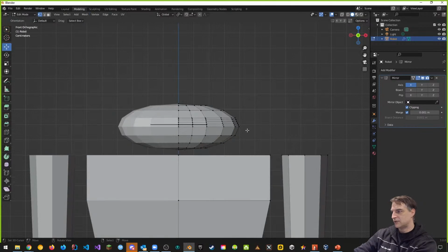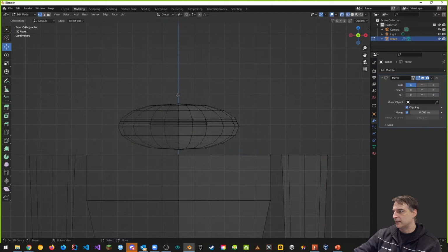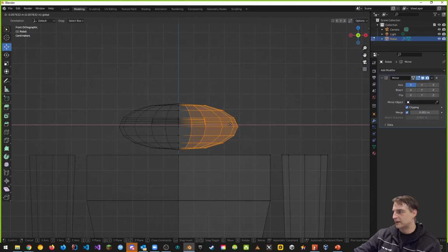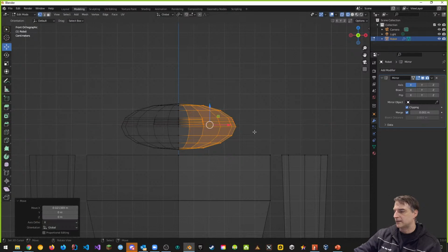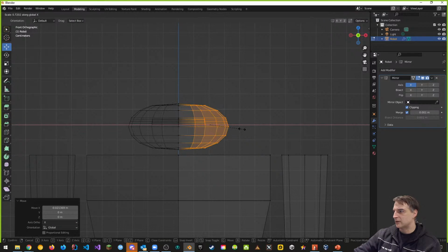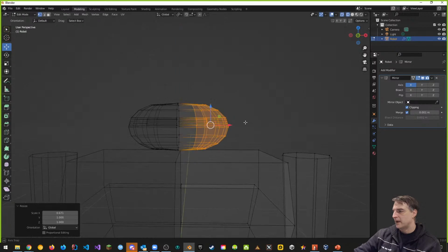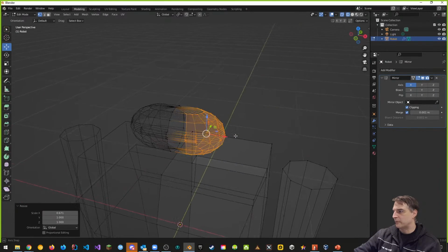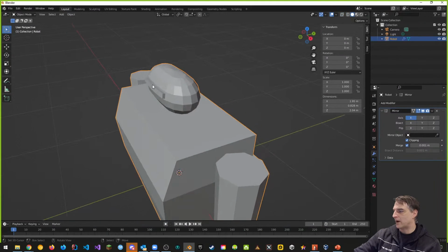If you want to change the head shape, go into wireframe mode and select the head from the middle vertices, just from the middle verts here to the right. Once you select those vertices, you probably want to bring it in just a touch and scale across the x-axis. If you scale across the x-axis, you can bring it in a bit more, and it'll look a little better than what we had before. The only problem is the way we did the eye. If I go back into layout mode, you can see that the eye is quite wide now.